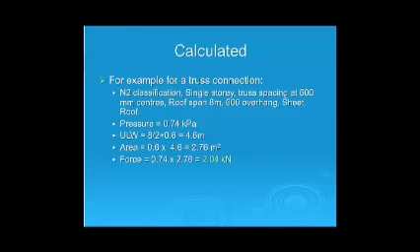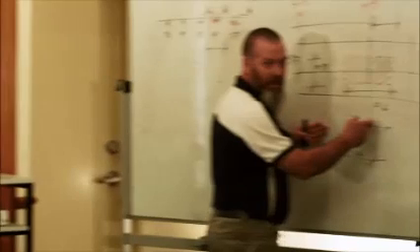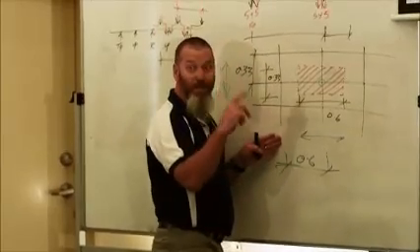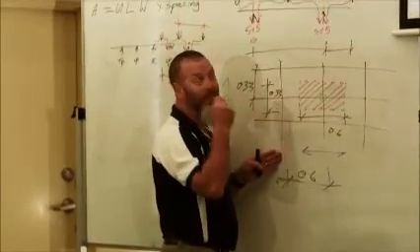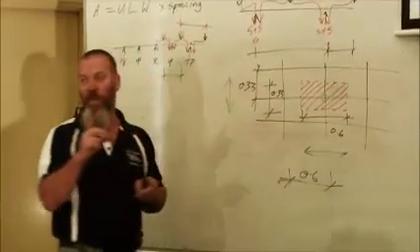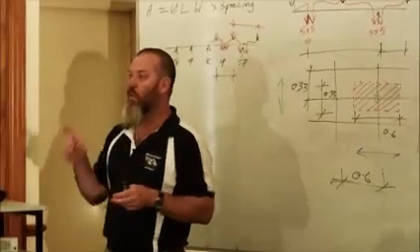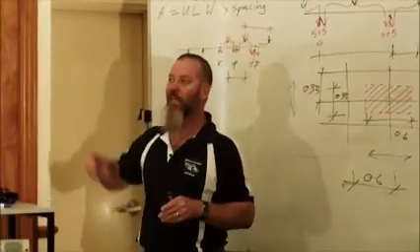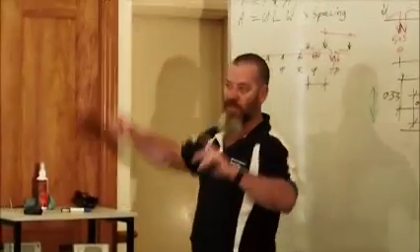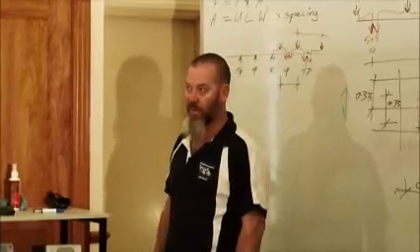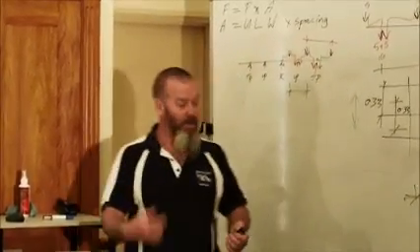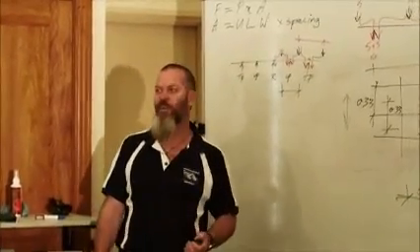Secondly, where it says truss spacing at 600 centres, obviously that's the distance that the trusses are apart. So that will be the distance between connections, 600. And the roof span is 8 metres. What that actually should say is the distance between the connection on that side of the building and the connection on that side of the building. So already you can see the pattern forming here, I hope.